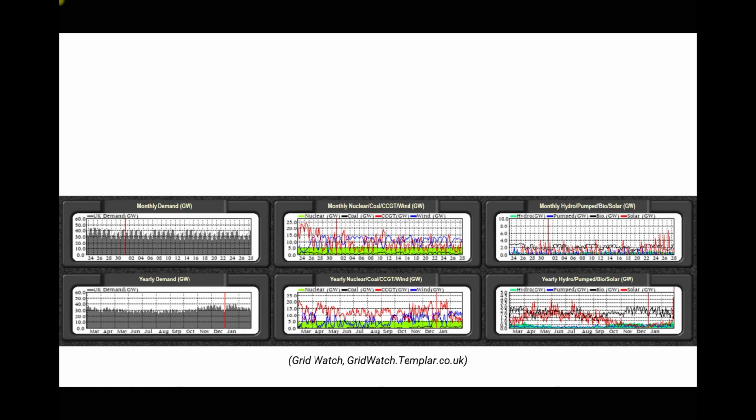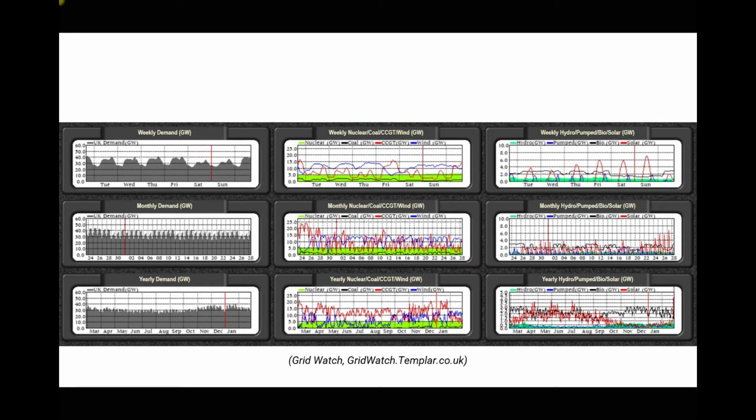Let's break these increments down a little bit further then. Here we have the demand during the week. Now, as we said before, we can see that the demand on Saturday and Sunday is slightly lower than Monday, Tuesday, Wednesday, Thursday and Friday. But what we also see is throughout the days, the energy demand fluctuates. So we have when people are sleeping, and then they get up to go to work and we have the working day, and then when they get home, we see another spike in the use of energy. And this trend continues throughout the week. We see a similar trend at the weekends where the demand in the morning is perhaps somewhat lower than in the afternoon and evening.